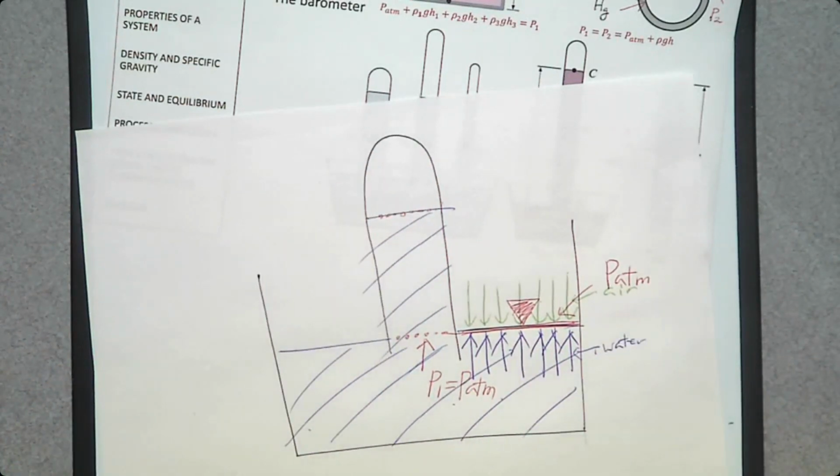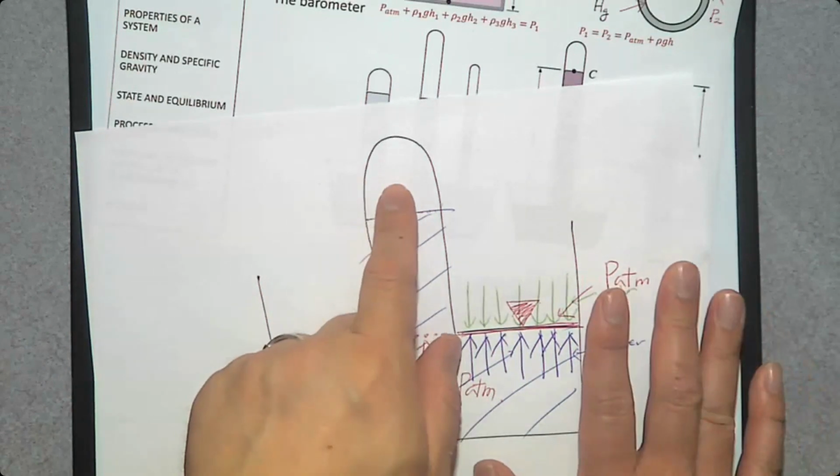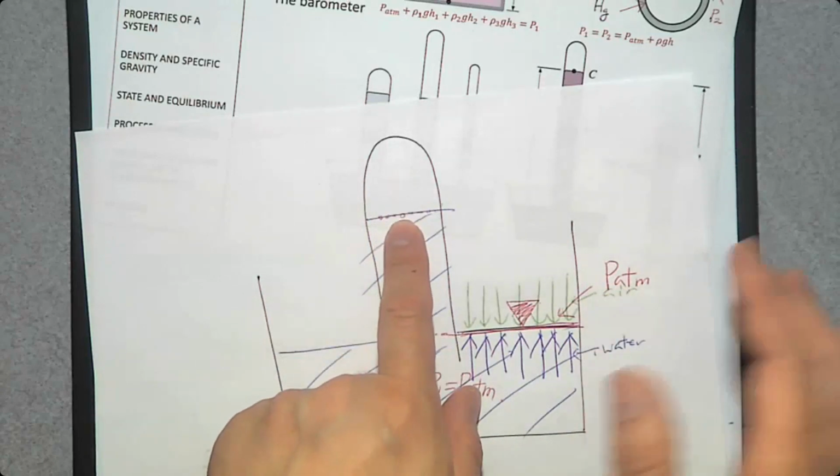Yes, vacuum. What is the pressure by vacuum? What is the definition of pressure? Force by fluid. Then what is the pressure value by vacuum? Zero. So the pressure at this point is going to be zero, practically. Water vapor is possible, but a very small amount, unless you increase temperature or decrease pressure. So at the typical atmospheric pressure, we can neglect the effect of water vapor. So pressure at this interface is going to be zero.